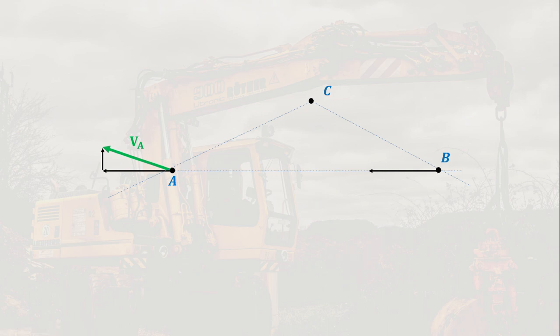If we already know that the direction of B is along this line, say for example that it is given in the problem that B is known to move in this direction, then we can get its absolute velocity by drawing a line from its head, connecting it to the direction, and using head to tail, we know that the third side would be the absolute velocity. So the velocity of B would be in this direction.